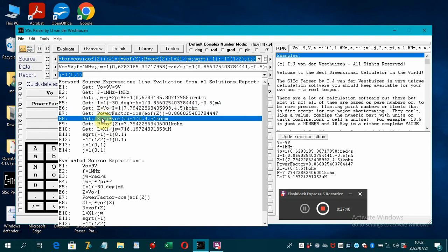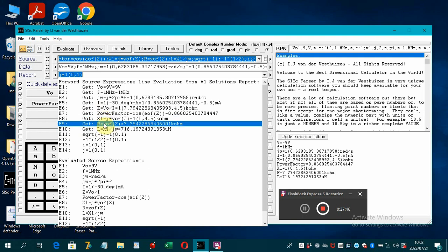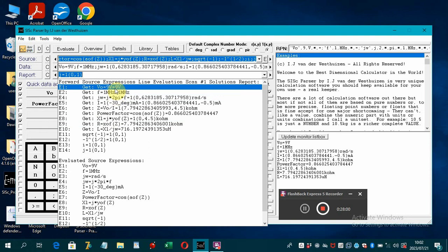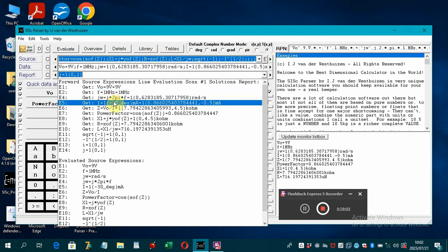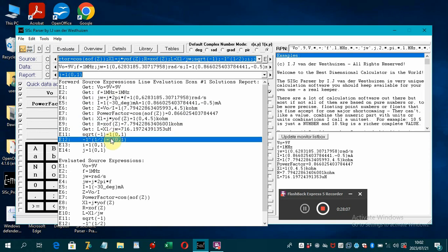And X is purely the coil's effect, the component of that resistance, and R is the real component, or the resistor. A resistor is also always real. It has no phase angle. The voltage is in phase with the current, or the current is in phase with the voltage basically. We assume a zero phase angle on the voltage, and the phase angle is always given on the current in electrical engineering normally.